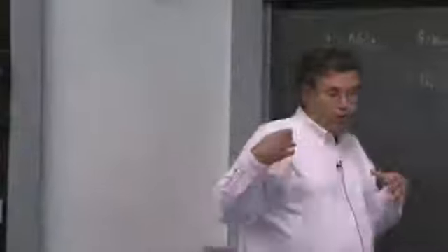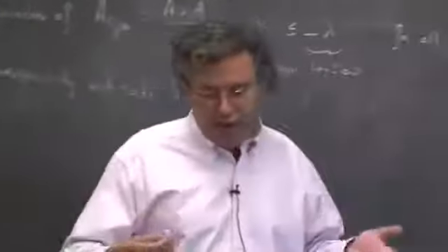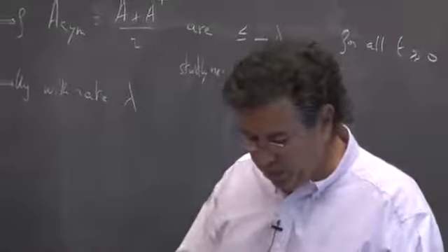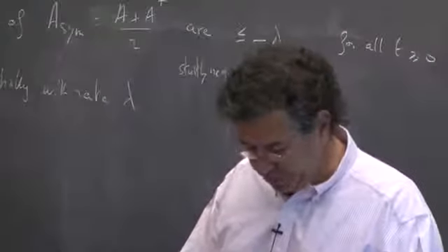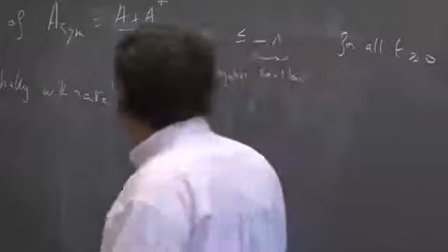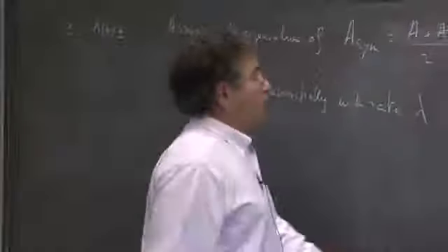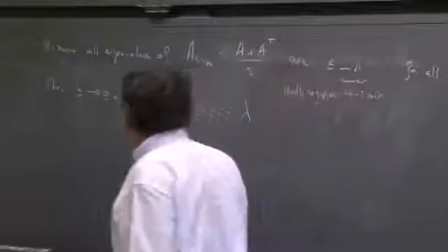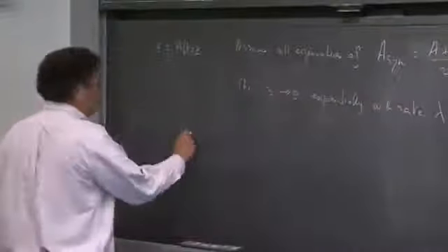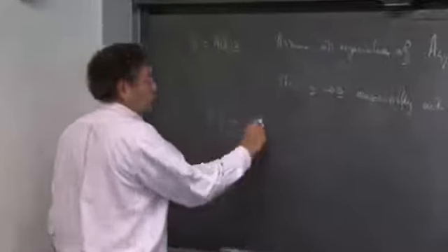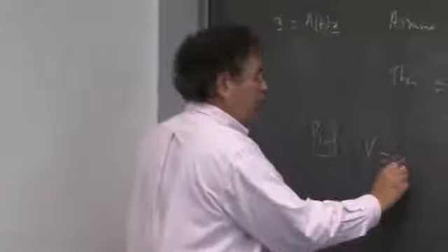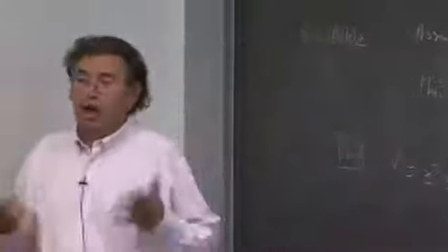How can we show this? Well, basically we can use Lyapunov's idea, but without really invoking Lyapunov theorems. So how can we do this? We're just going to pick a scalar function, which we'll call V, and the scalar function will just be the norm squared, x transpose x.